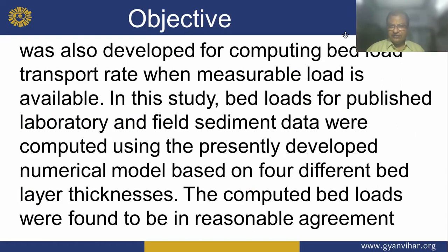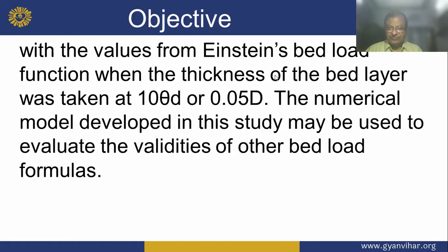In this study, bed load for the published laboratory and field sediment data were computed using the presently developed numerical model based on 4 different bed layer thicknesses. The computed bed loads were found to be in reasonable agreement with the values from Einstein's bed load function when the thickness of the bed layer was taken at 100 tan theta d or 0.05 d.